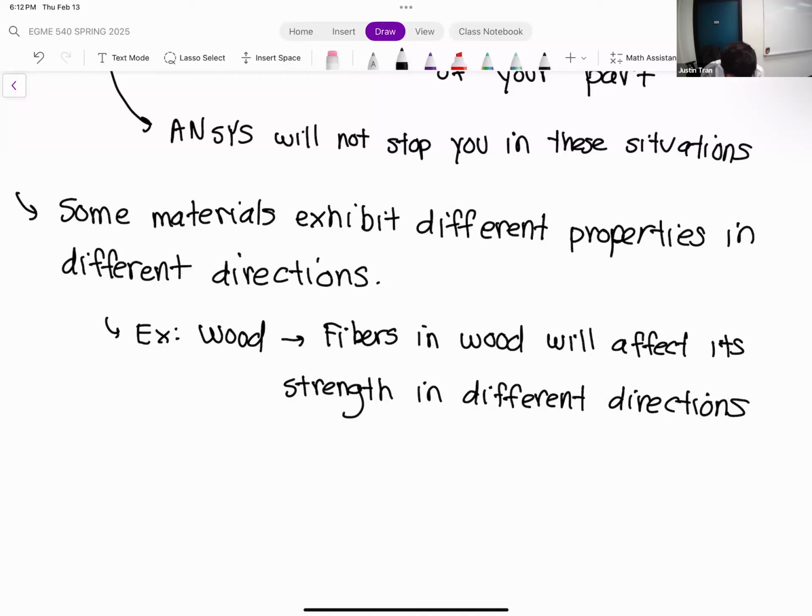And now, of course, that doesn't include particle board or compressed wood that's made from sawdust. And so this is kind of natural. All right, so another common material that has different strengths in different directions are certain kinds of composite materials as well. Carbon fiber is also a very popular material in aerospace applications. That one also has different material properties. 3D printed materials, so additive manufacturing, especially ones that are built layer by layer, are also going to experience different properties in different directions.